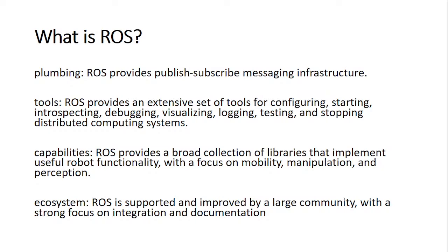So it can easily move based on that. You can take those velocity values and apply them to the motors, and it will move based on those values. Here the single board computer is controlling the microcontroller by sending velocity values through this method called publish and subscribe.